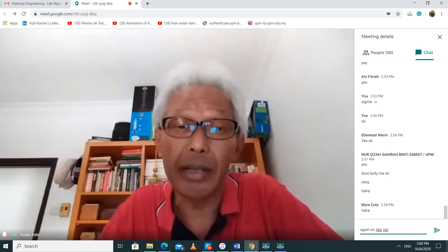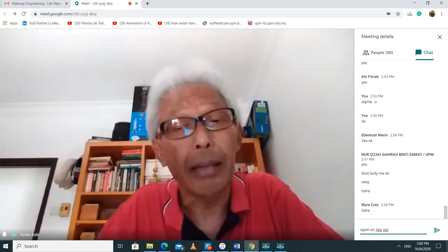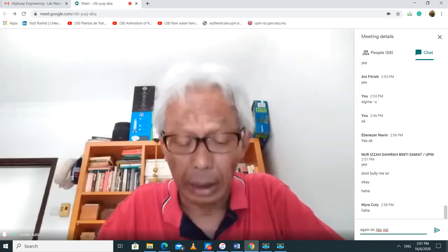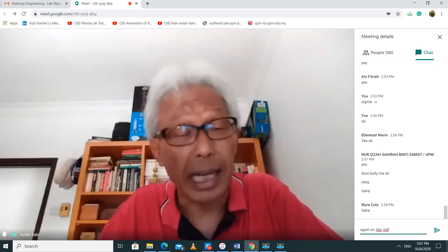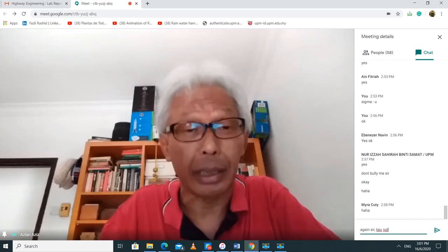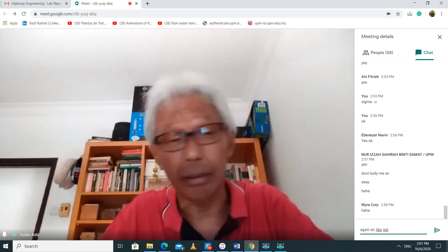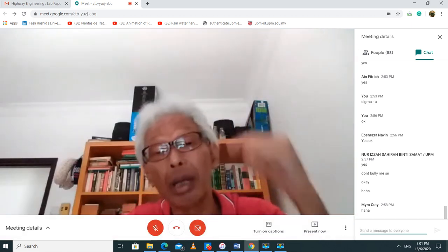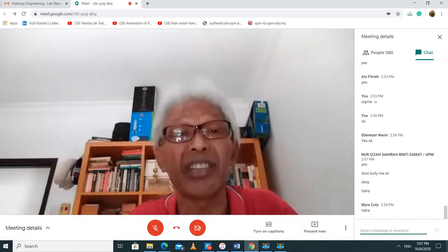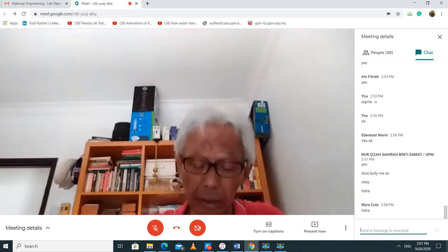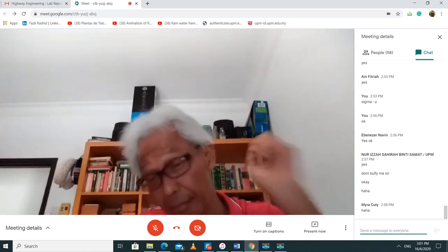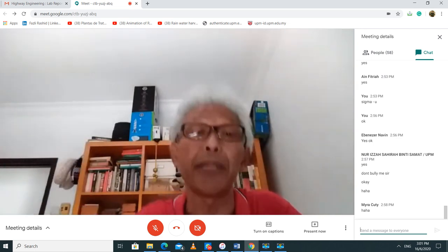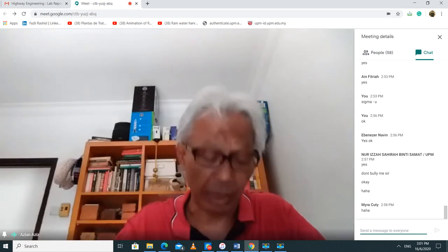Now the question is, why is there no Q prime? After all, the principle of effective stress applies all the time. It doesn't matter whether you call it Q, P, or whatever, because stress minus water pressure will give you the effective stress. The bottom part of page 9 shows you that the value of sigma prime 1 minus sigma prime 3 divided by 2 is the same as sigma 1 minus sigma 3 divided by 2.